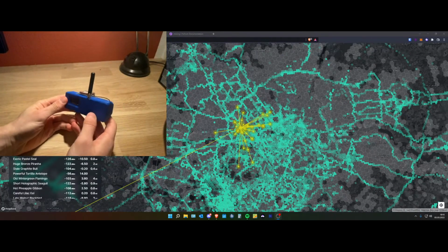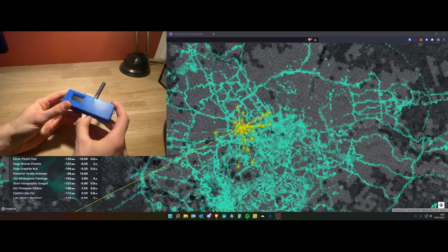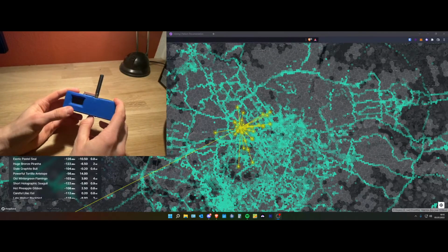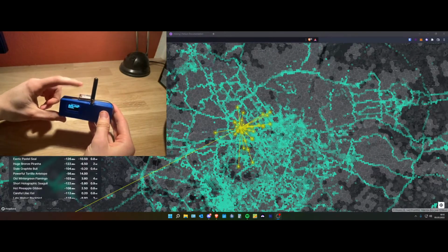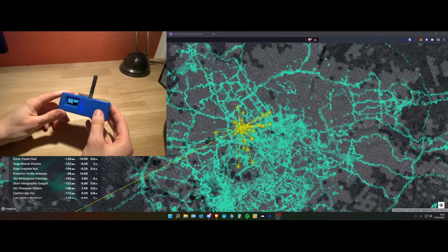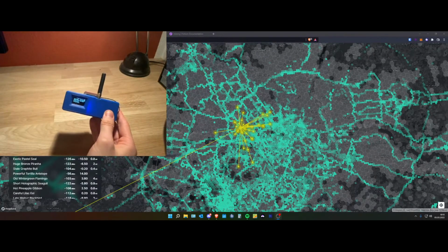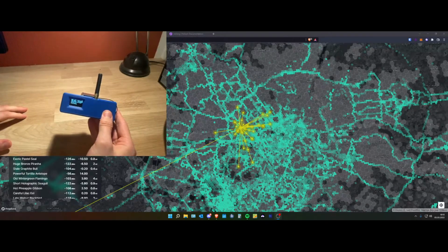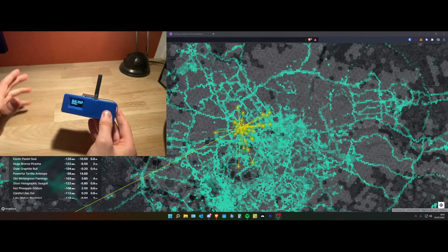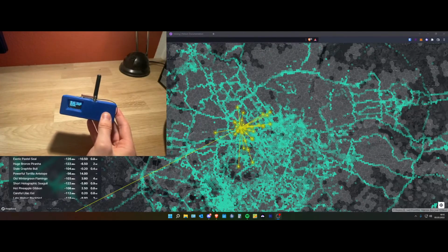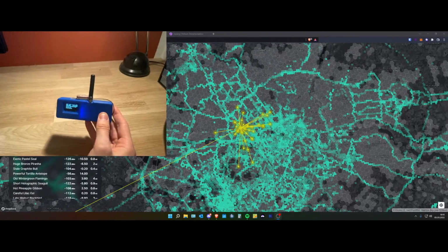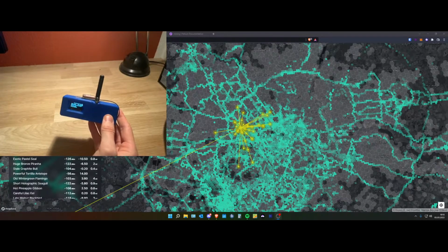This is basically what a mapper looks like, and you're really just turning it on. We've got a little LoRaWAN antenna on top here, and this one is a GPS antenna. If you have installed and set it up correctly, you just need to power it up, and you can go straight out and track around the world, and you will create some of those little green hexagons that you see on the map, and you can find out if you provide coverage to a certain position or not.